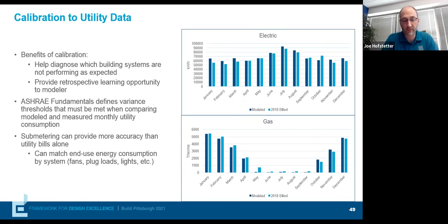And during construction, it was determined that was a little bit harder to get to. The lead times were longer and costs were a little bit higher. So it was proposed to put in more of a channel system that used an aluminum channel or some kind of metal channel system to hold the continuous insulation in place. Not thinking much of it, they were going to approve it, and they just happened to ask for our opinion of it, and we ran it in our tool.